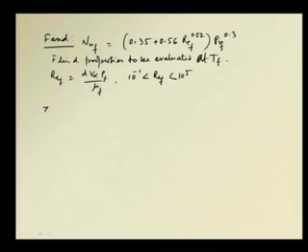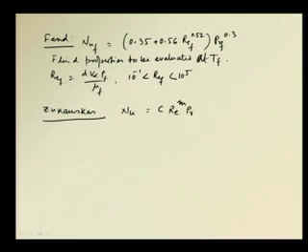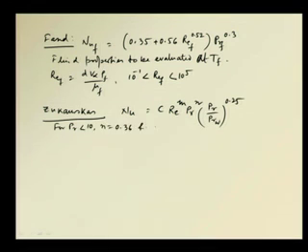Okay. Then Zhukauskas has given a relationship which says that Nusselt is equal to some constant C into Reynolds to the power m into Prandtl to the power n into Prandtl by Prandtl_W, so the evaluation conditions are represented over here. For Prandtl less than 10, n is equal to 0.36, and for Prandtl greater than 10, n is equal to 0.37.